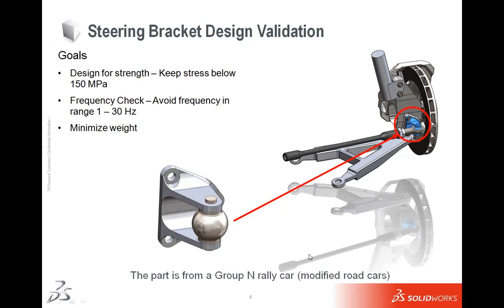So let's go back to the PowerPoint. Now, with our brand new design, we have minimized the weight, we pass our frequency check, and we also pass for strength. I could have also done something like a safety factor. If I want a safety factor of 2 or 3, I could have added that in. If I wanted to change more than one dimension, I certainly could have done that as well.